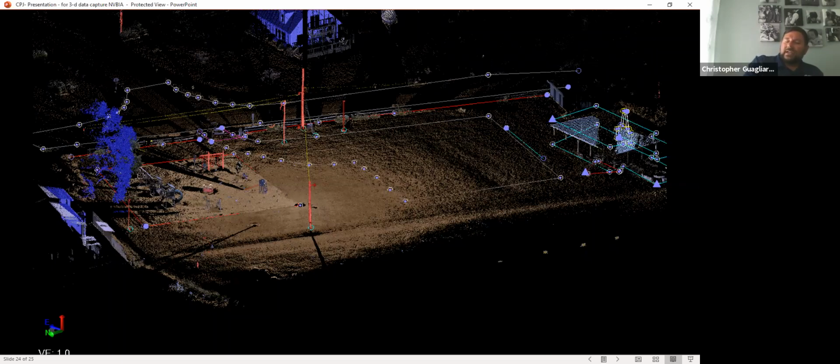But usually one that's got about 64 gigs or more, because most of the scans you're doing are going to take up a lot of space. It's usually about 20 gigs per scan if you're doing any more than 5 setups. So that's when you need to have a card. It does not have an internal memory on it. It just scans. That's all it'll do.